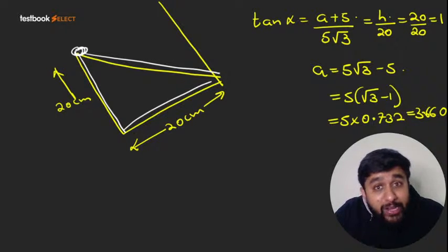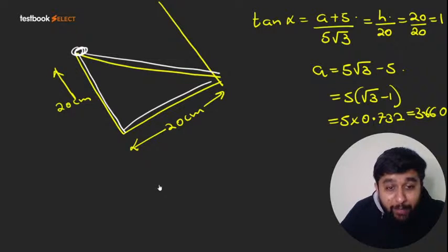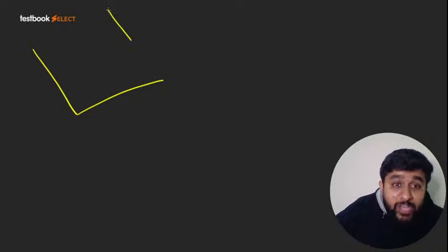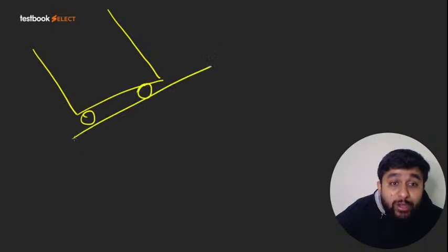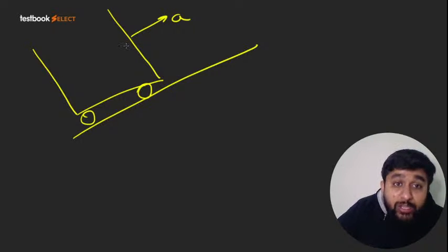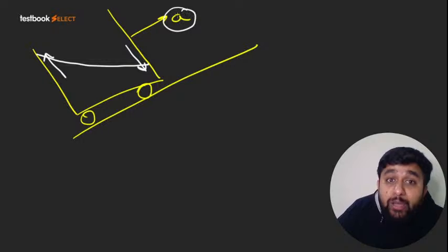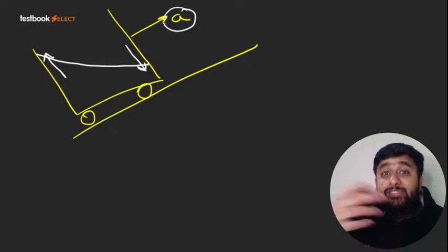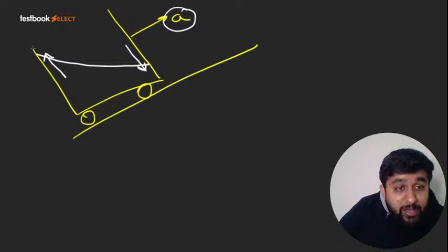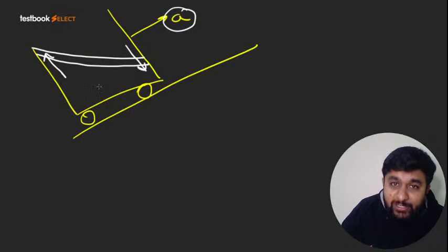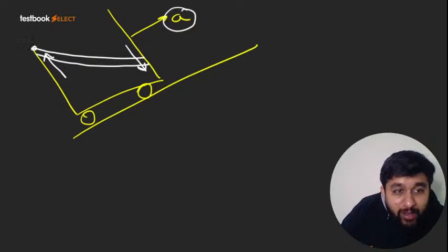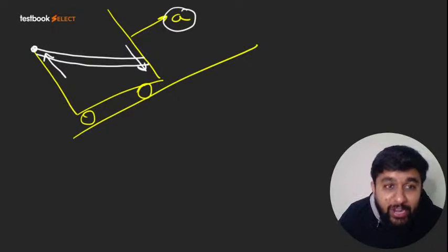सो मैं फटाफट से क्विकली आपको मेथड रिवाइज करा देता हूं. So देखो मैंने क्या मेथड सॉल्व किया. So guys, in the question it was said that the container is moving on an inclined plane with the constant acceleration. So we know what will happen. Water in the front will go down, water in the back will go up, and finally water will achieve a constant shape. Now it says what should be the maximum acceleration so that the water is just about to spill out. This means final shape of water will be something like this. This point will intersect with the top point of container, है ना?